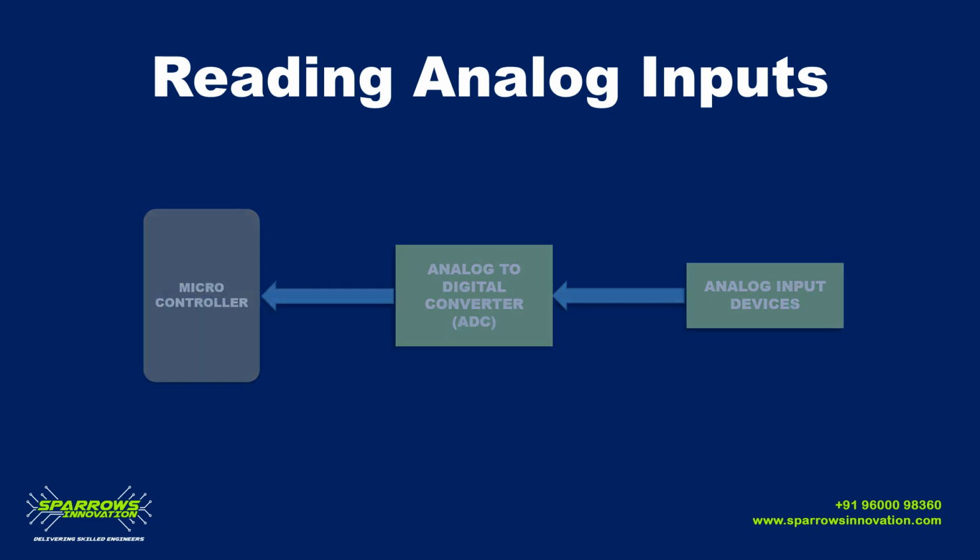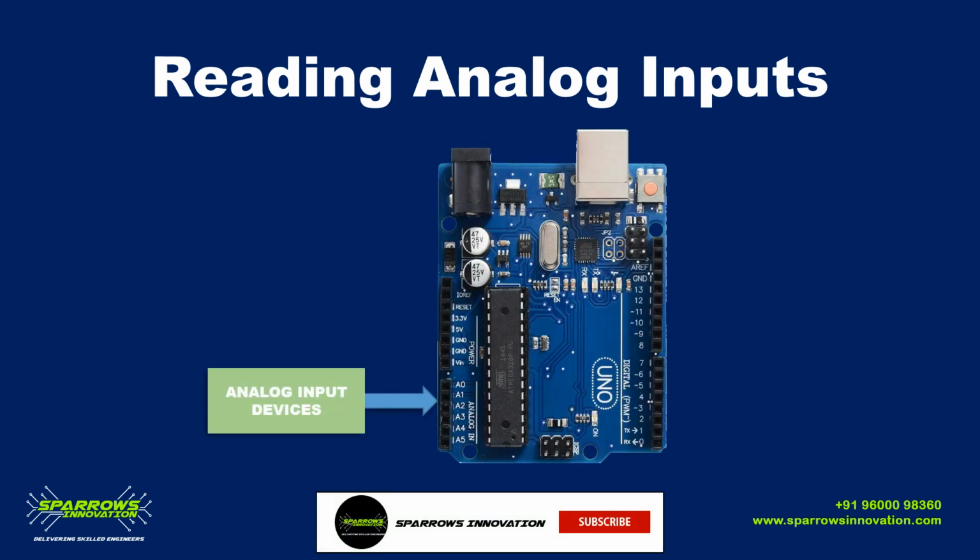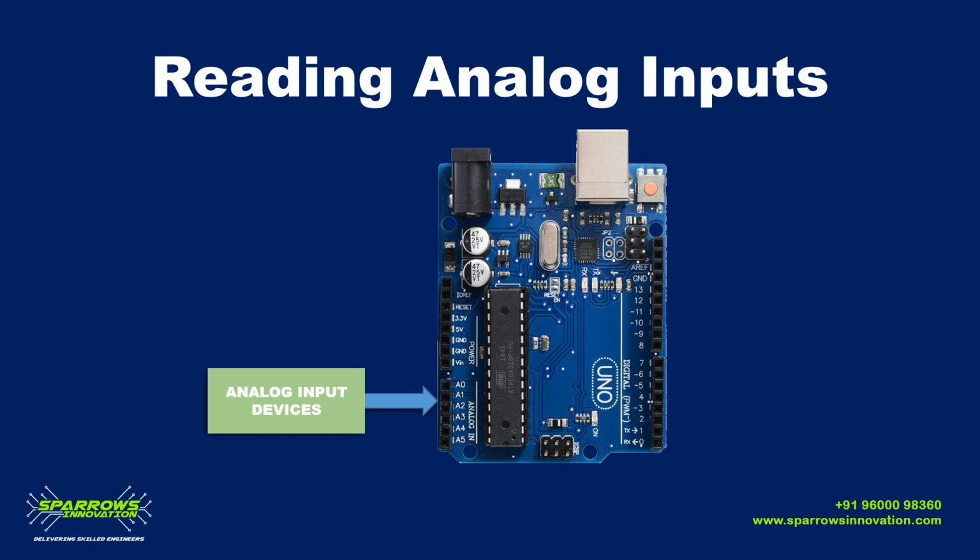In the same way, with Arduino, you can directly connect the analog input devices to the analog pins of your Arduino, A0 to A5, because nowadays all the microcontrollers have an analog to digital conversion block inside them.